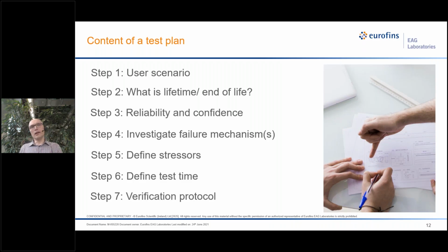The user scenario leads to the discussion about lifetime and what is exactly end of life. I mentioned already a statement about reliability and confidence, but here it's also important to discuss what the reliability and confidence level should be. If this part is clear, we will investigate the relevant failure mechanisms and transfer it, defining the right stresses. Based on the expected real lifetime, we can calculate the test durations.